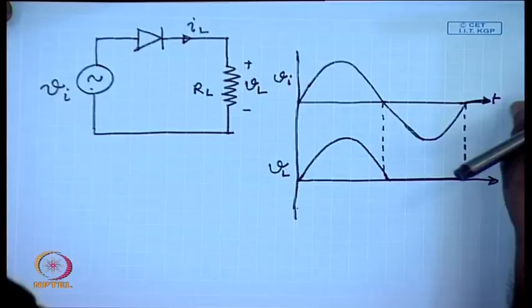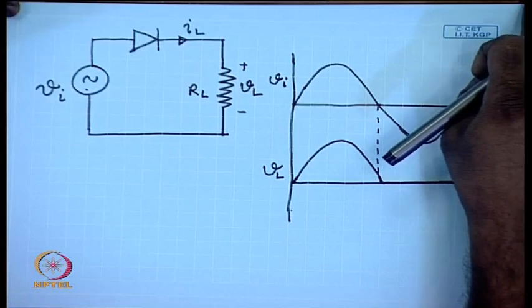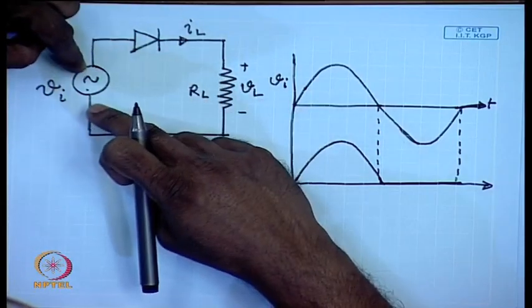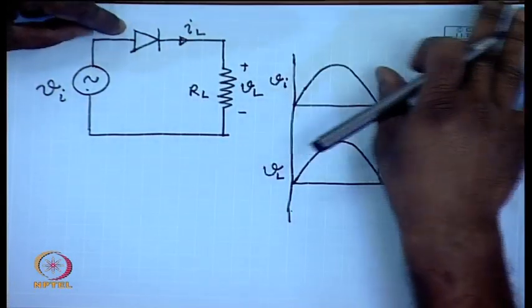While a diode is a useful switch, it cannot be turned on or off by a control signal, that is, the conduction interval of the diode will be solely determined by the voltage across it. It cannot be controlled in any other manner. There are other switches in which that is possible.